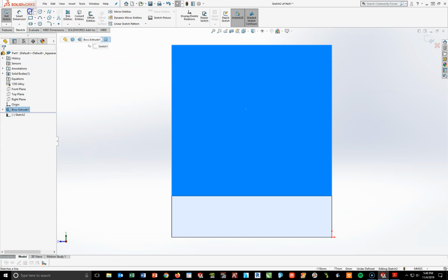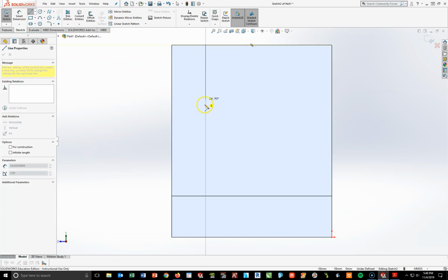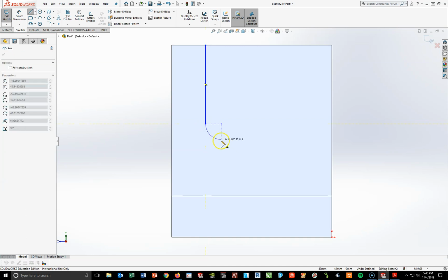Now, turning on the line tool, I'm going to start at the top and pull straight down. Now, I'm going to show you a trick here that you haven't seen before. I'm going to take my line tool and slightly pull away. I'm not going to click anywhere. I'm just going to pull away and then come back and touch the end of a line again. And when you do that, your line tool will automatically create an arc. Now, if you click and the arc is going the wrong way, do that one more time. Actually, it's going to do it either way. It's fine. Oh, like something like this, okay, where the mistake is it's getting too big. Just come back and touch again, and it will end up shallowing itself out.